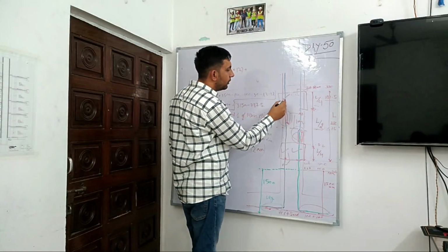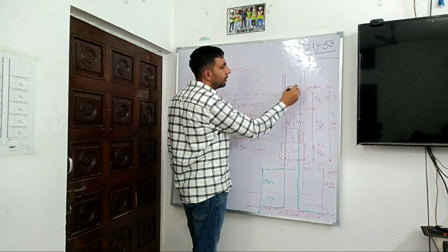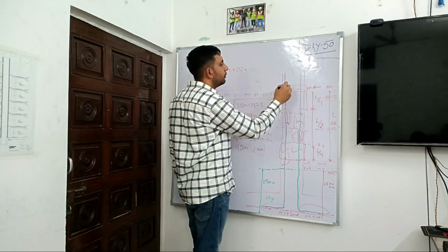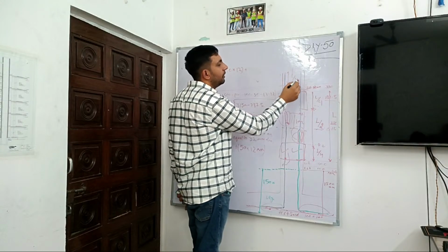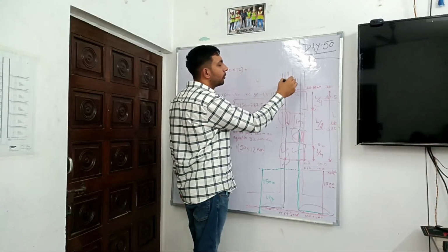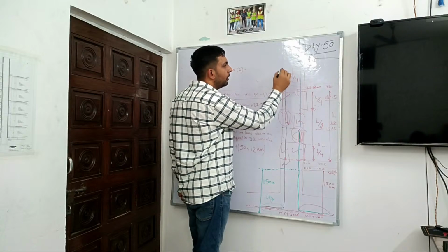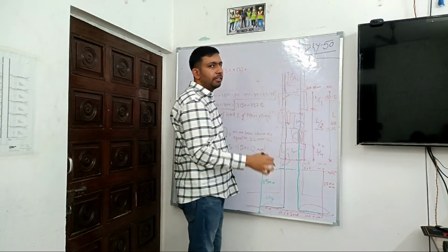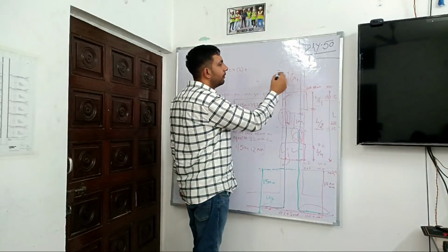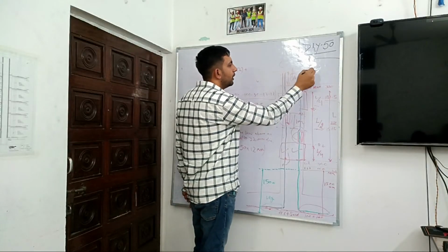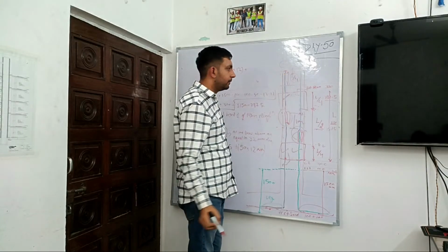Then we will go this way, then this, and after crossing the slab beam, above L by 4, the height of the column divided by 4, we will provide a lap if we are continuing to another level, or if we are done at this floor, then we will go to the top, subtracting the cover.